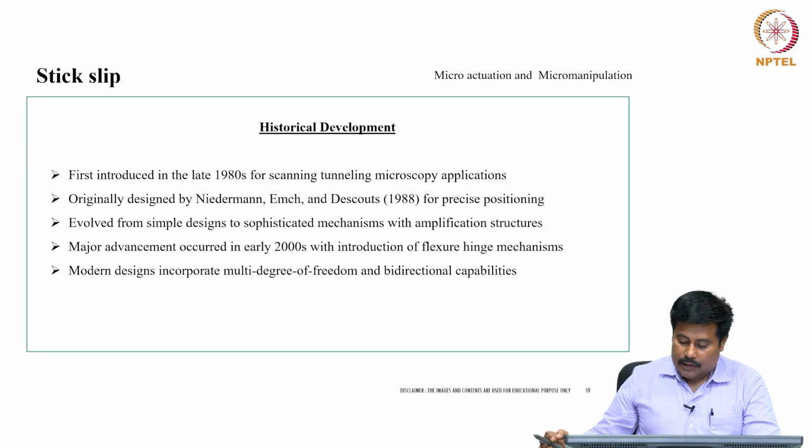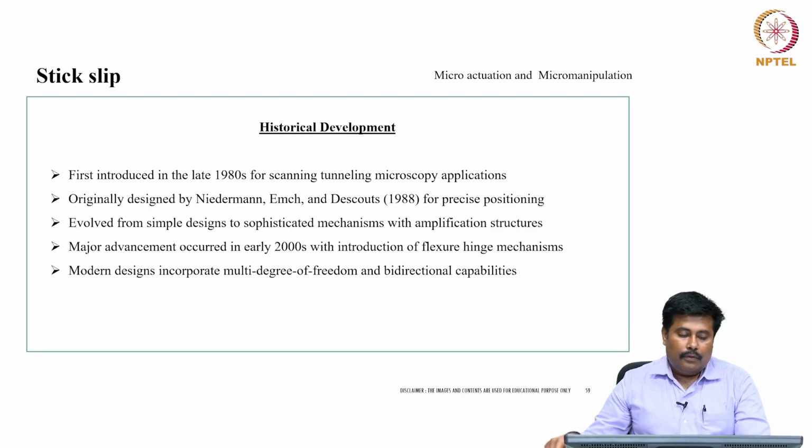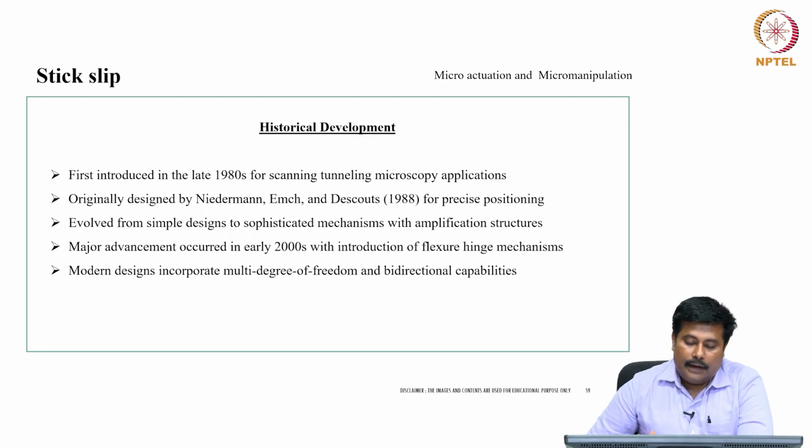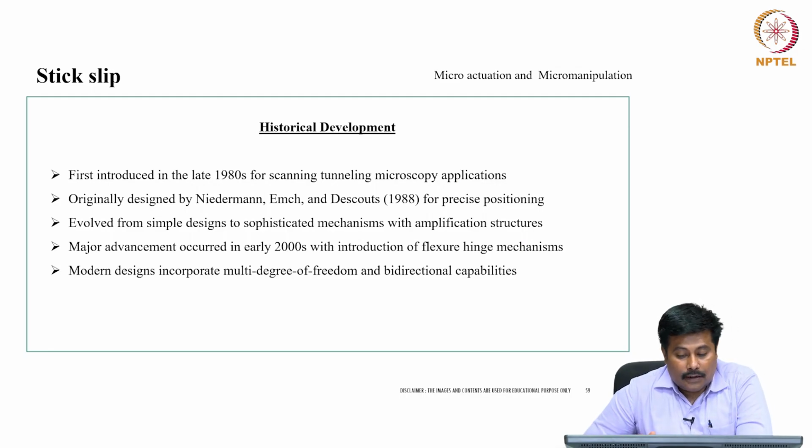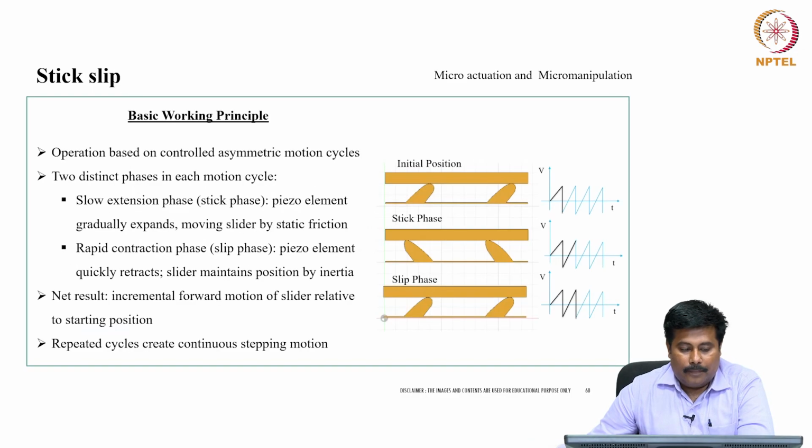From a historical development point of view, it was first introduced in the late 1980s, basically for scanning tunneling microscopy applications. Originally the stick slip phenomenon was designed by Niedermann and Emsch for precise positioning, and it evolved from a simple design to a sophisticated mechanism with an amplification structure. The major advancement occurred in the early 2000s with the introduction of the flexural hinge mechanism. Modern designs incorporate multiple degrees of freedom and bidirectional capabilities.